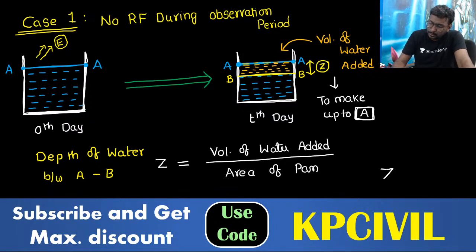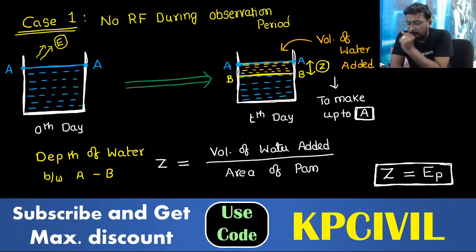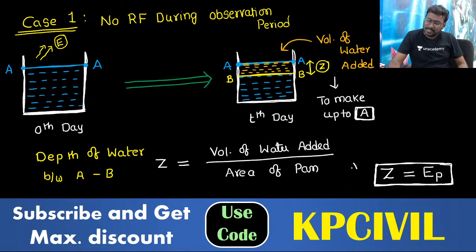In this case, as there is no rainfall, Z is equal to pan evaporation. If rainfall is there, conditions will modify. But here no rainfall, only evaporation. Directly you take Z is equal to EP. Is it clear for everyone? If there is a rainfall, then we can calculate, either add or subtract or do something. Here there is no occurrence of rainfall, only evaporation will take place. So directly we'll consider Z is equal to EP as there is no rainfall.